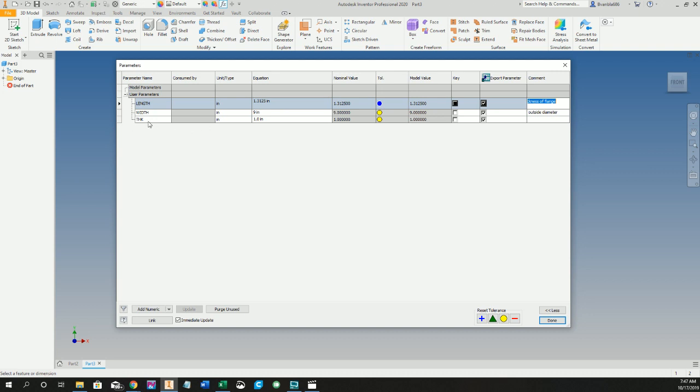The thickness, I'm actually going to do the thickness of the flange itself, not the raised face part of it, not the weld neck part of it, but the thickness of the flange itself, which is 15/16 minus a 16th for the raised face. So we're going to go 0.875 and type in here thickness of flange body.